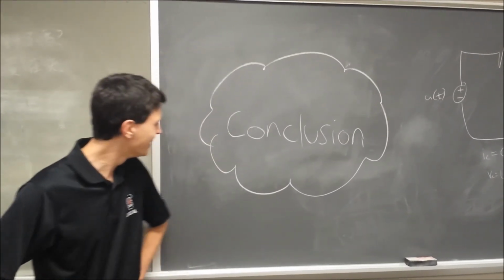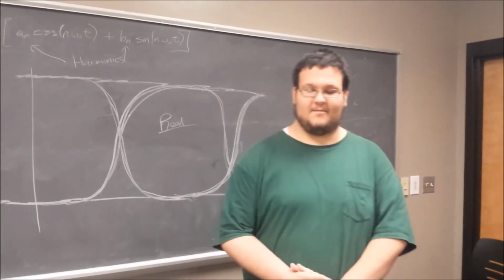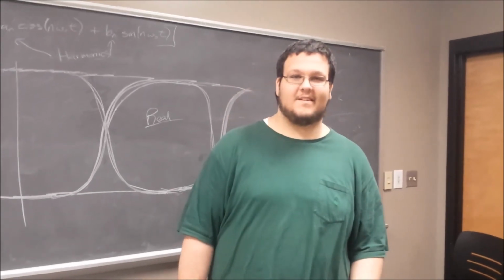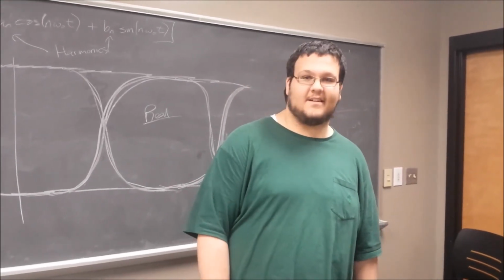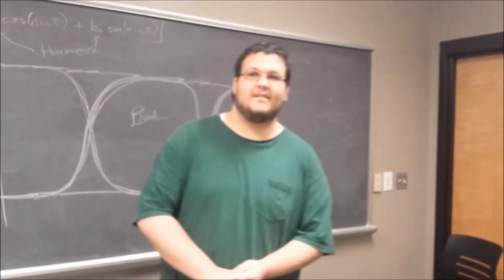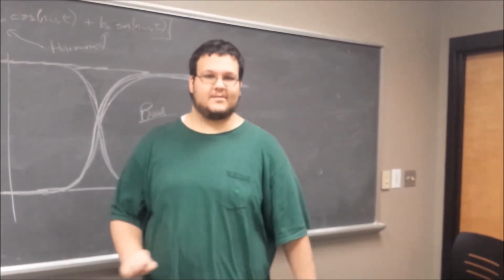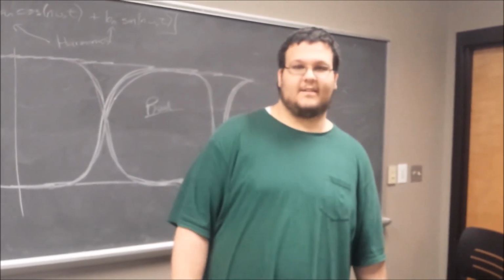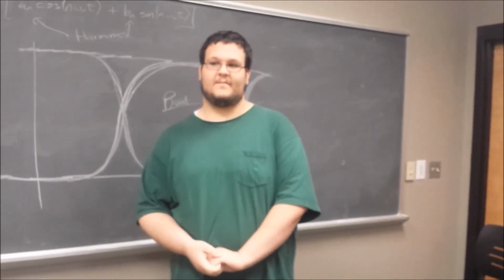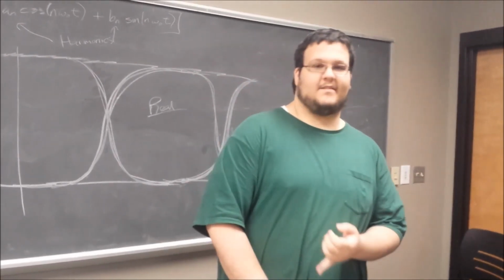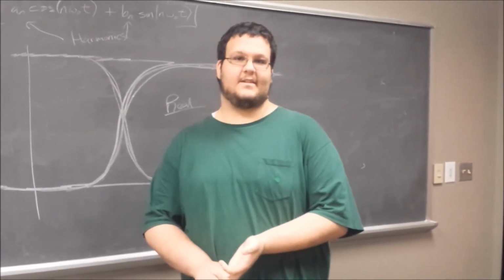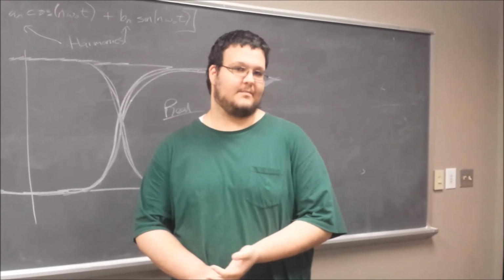It worked! So basically, we were able to model the parasitics using a second-order low-pass filter with the resistor, inductor, and capacitor, and see that at certain values for capacitance, the bit stream was distorted, where not every bit was read as correctly as a 1 or a 0. And as for recovery methods, maybe possibly reduce parasitics or have a better algorithm to register the rate at which the bit stream flows.